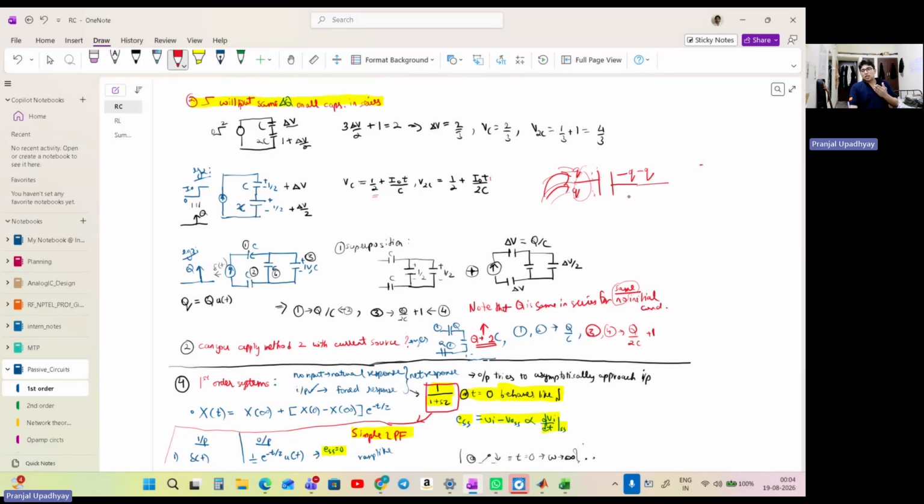And so the current will flow, because as you can understand, here is another circuit, here is another cap. Since Q is being pumped here, this Q will attract minus Q over here, and because of this minus Q, plus Q charge will get created here, and again because of this, minus Q will get created here. So in a way, a current will keep on flowing still, right? It will appear as though the current is still flowing, because the capacitor has not reached a steady state because of this current source injecting current constantly. So that is the idea of a steady state, that a capacitor will block steady state current. But here, the current source itself is not allowing any steady state condition to appear in the circuit, right? So that is the basic idea.